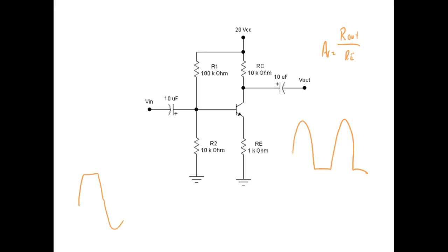But what we want to do is keep all these formulas that we got, and add more gain to the transistor. The problem is my input signal has to come in, and it's got to go through that resistor right there. So that guy right there is what's limiting the gain. If I can make that guy really small, then I can get extremely good gain. But if I make it extremely small, my bias current goes way up, right? You understand? And the whole amplifier gets out of whack. So what we would like to do is come up with some type of method where the input signal does not have to go through my emitter resistor.